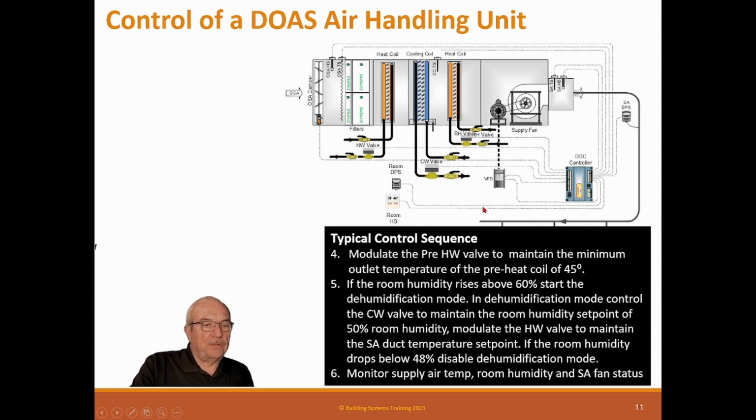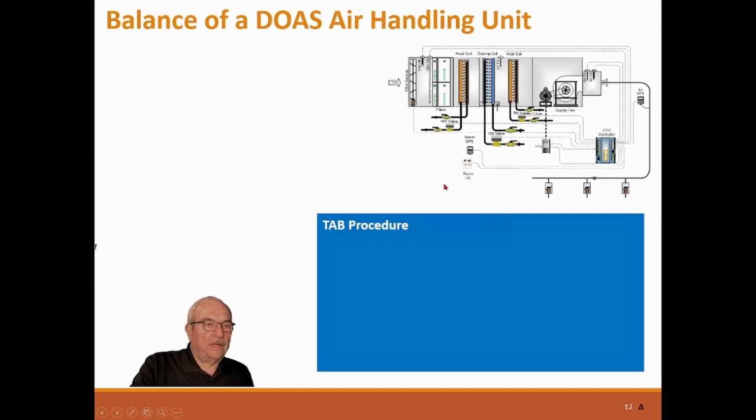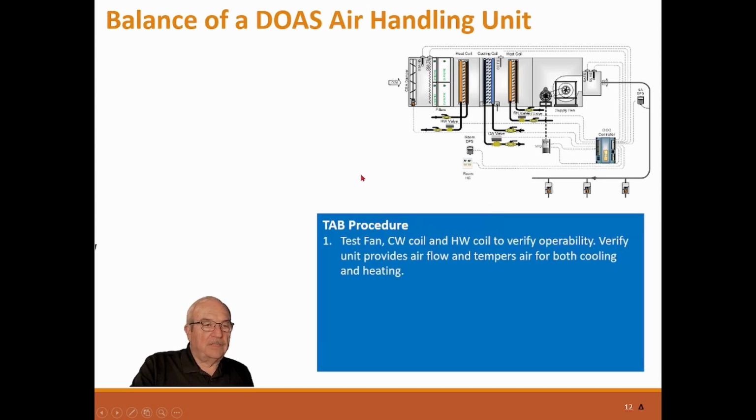Monitor supply air temperature, room humidity, and supply air fan status. Okay, how do you balance one of these? Test the fan, chill water valve, hot water valve to make sure it's got air and it's got temperature control.